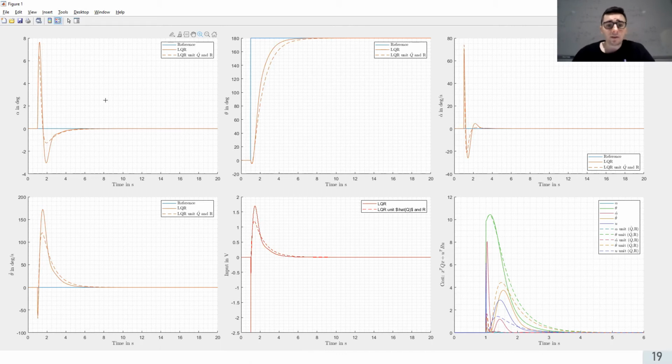If, for example, your system shows a really strong, undamped oscillation in open loop, then probably you want to put a lot of weight on the eigenmode that corresponds to this oscillation. Usually you have two eigenmodes if you have oscillation, but whatever, you want to put a lot of weighting on this oscillation. Here, there is no such oscillation apparently, so the first eigenmode is what you have if you weight the first eigenmode, basically.